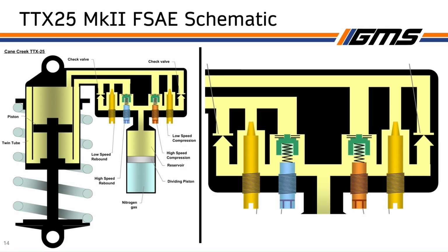So this is a schematic of the Öhlins TTX25 Mark II FSAE shocks. This is a pretty common shock for FSAE teams to use. This is what Gator Motorsports uses at the moment. And so I'm just going to real quick run through how the internals of this guy work. So you've got a reservoir here, right? You've got that cylinder full of oil.